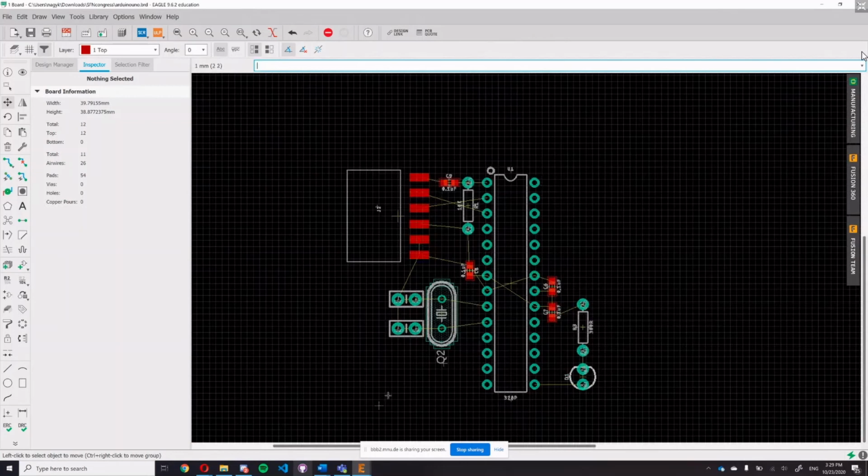So now I would draw the outline of the board, so we can have an outline. I would select the line tool down here. Some of you may have a smaller monitor, and you will need to press this thing to expand, and you will have it somewhere on this panel. So does everyone have the line tool and also the layout completed?